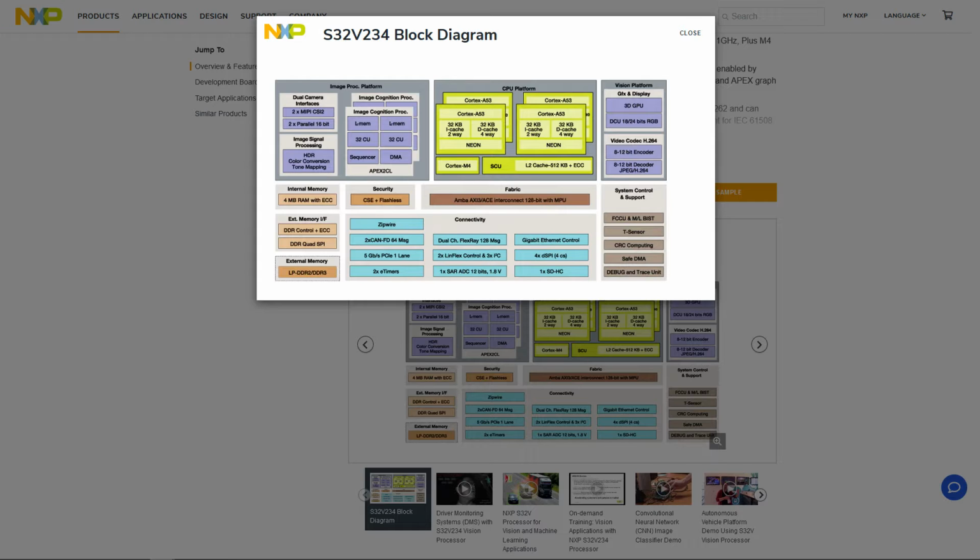But beyond that, it's also got the capability of handling 2 MIPI CSI2 connections. So you can virtually connect a couple more cameras, and I think it would have the capability of handling at least 6 cameras for sure. It's also got 2 parallel 16-bit camera inputs. So if you have 4 camera inputs per MIPI, you technically could have 8 cameras with 1 megapixel connected to the system, and we just need 6. So there is some room, some bandwidth, for further processing.